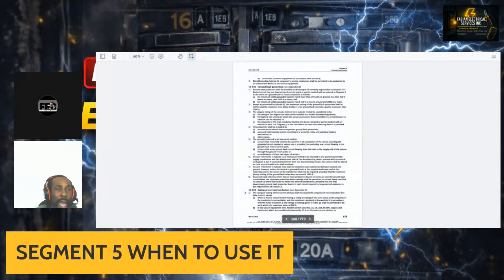Tonight's topic is again, electricians get this wrong: breaker sizing. Again, we're all human. So again, Rule 8-104, maximum circuit loading. Continuous loads must be calculated at 125%.